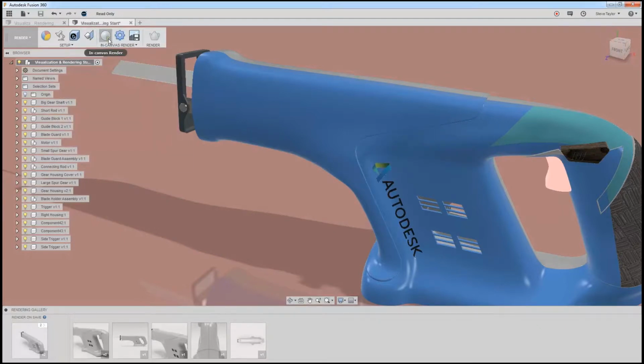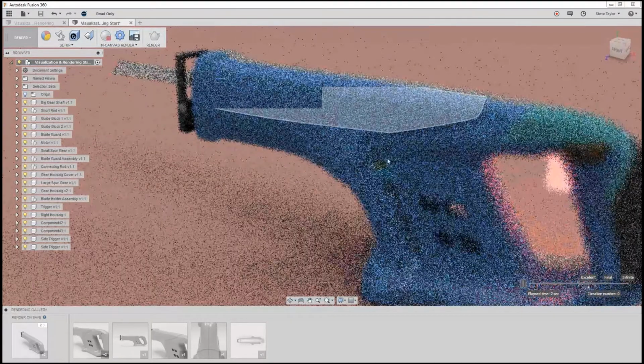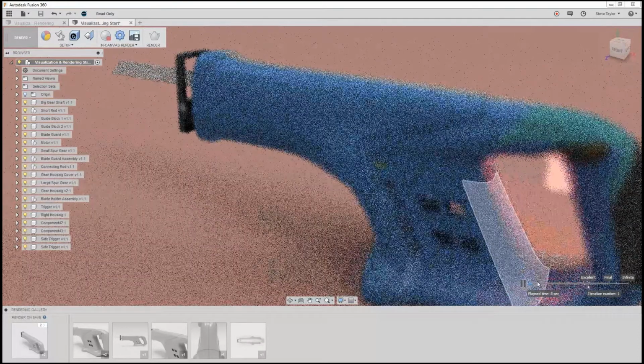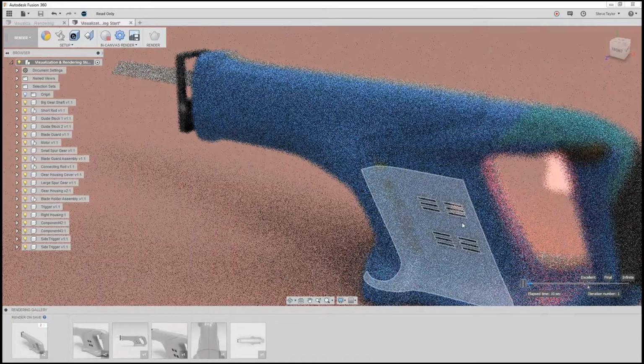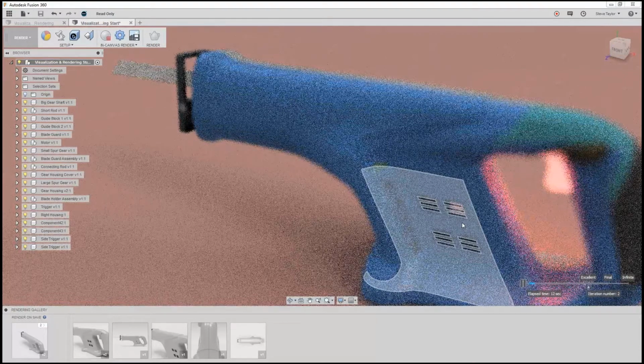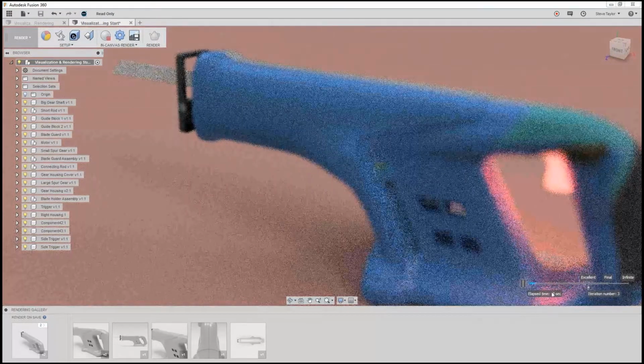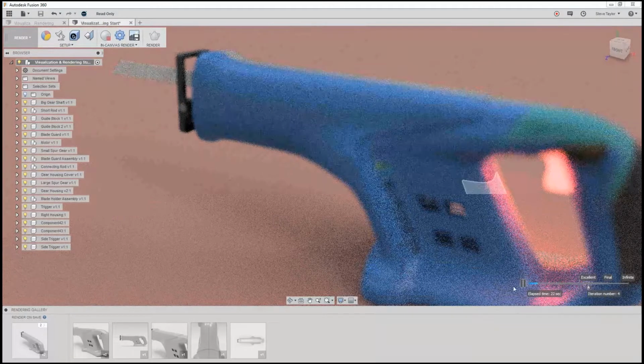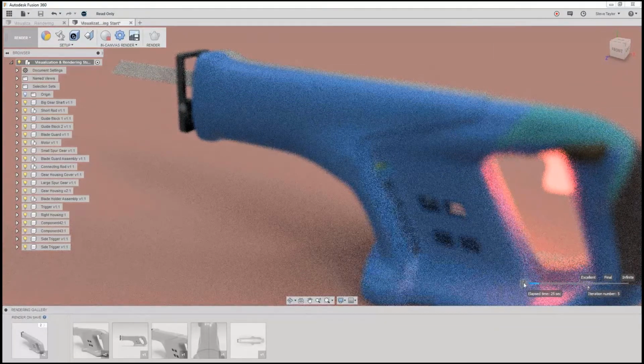In canvas rendering, this is what I was talking to about setting things up. If I went in canvas rendering, what this does, this actually starts the render tool, and when it starts doing iterations, and as iterations go, it gets finer and finer, the outcome. And you can see there, it's a time elapsed, the number of iterations that it's done through the design. Excellent is when we get to this point. We can pause at any time, the iterations.